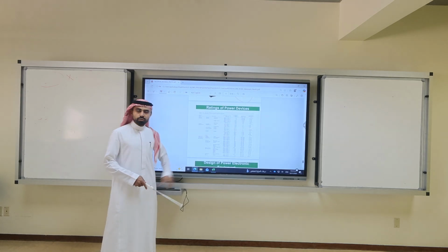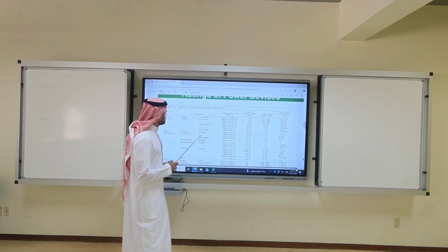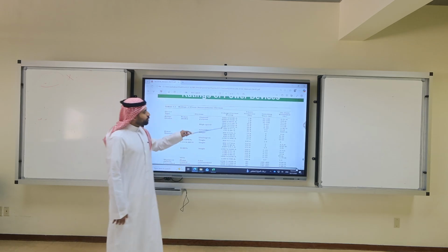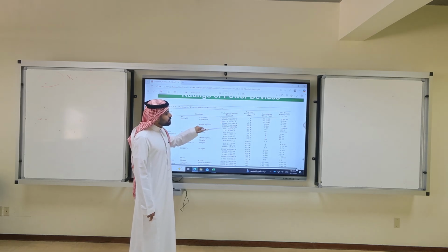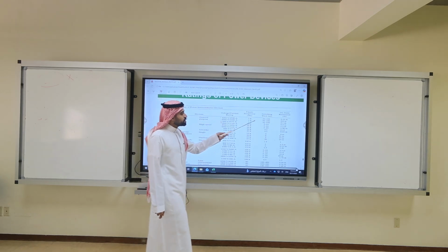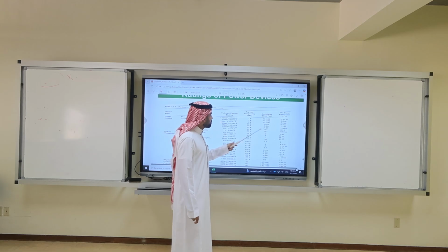What are the ratings of the power electronics? You can see the ratings for a power diode. I'm going to take one example, the power diode. The voltage is 4,000, 6,000, 600, 2,800. The upper frequency is 1 kilohertz, 20 kilohertz. Switching time is 50 micro to 5 micro to even 0.2 micro for very high frequency.